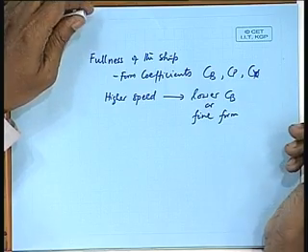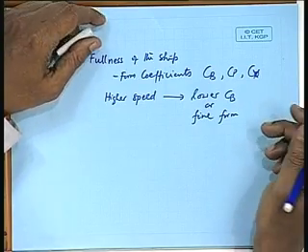That is the reason you will find bulk carriers and tankers are full form ships with high CB, and passenger ships, container ships, etc. are finer form. Now, you see, when I am talking of speed, I am essentially talking about Froude number, not speed as such.